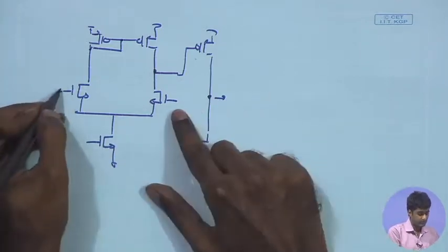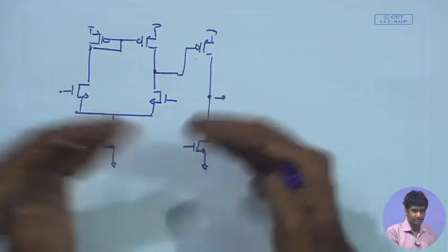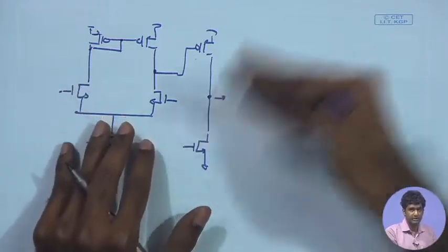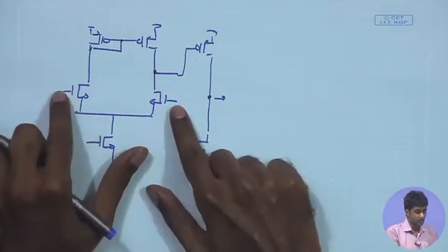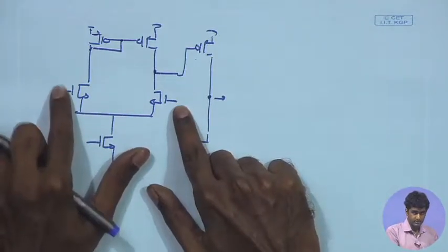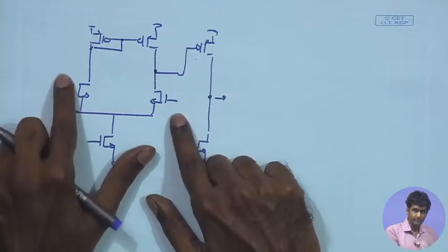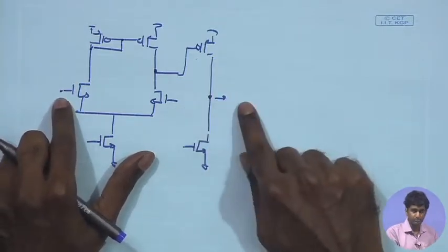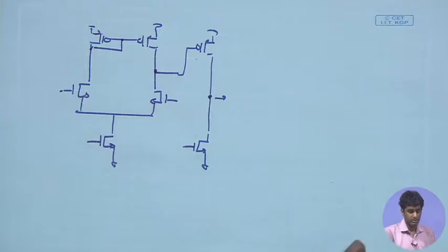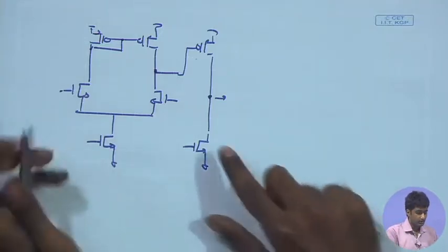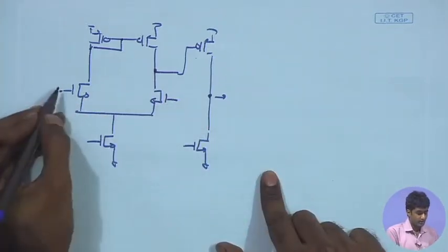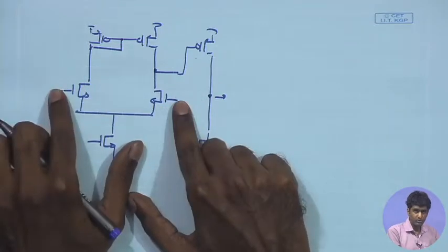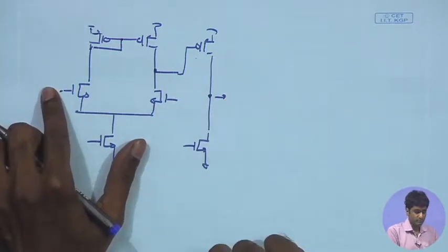Now, we have derived the specification for the gain of this amplifier when we are operating it as a comparator based on the ADC application, specifications of resolution and so on. There we saw that if there is a significant difference between these two signals, delta V, say in our case 15 millivolt, the output should go completely up or down to VDD or ground respectively. However, if there is a significant mismatch between these two transistors, how is the overall transfer characteristic going to change?